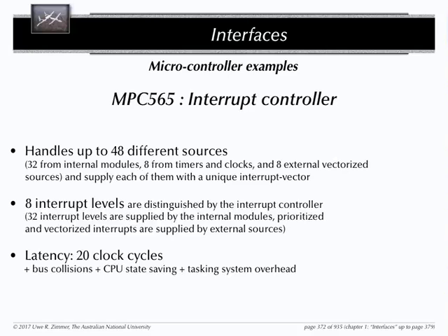So what you do instead is you have an interrupt controller which pre-filters, queues, puts hierarchy onto that, eliminates interrupts if they have been overwritten by other events. All of these things are handled for you by the interrupt controller, which, on the other hand, you of course have to program as well. So the flood of interrupts in modern microcontrollers has to be managed someplace. This is the way of doing that.